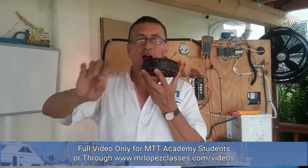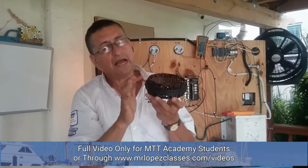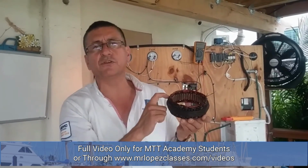We are going to verify with the tester, with the megohmmeter, if the winding is good or not good. Okay, for example, this winding is damaged. This is hot, neutral, and ground. This is the frame, and this is the winding. Remember, the winding doesn't touch the frame because it's separated with plastic insulation. The winding never touches the ground.